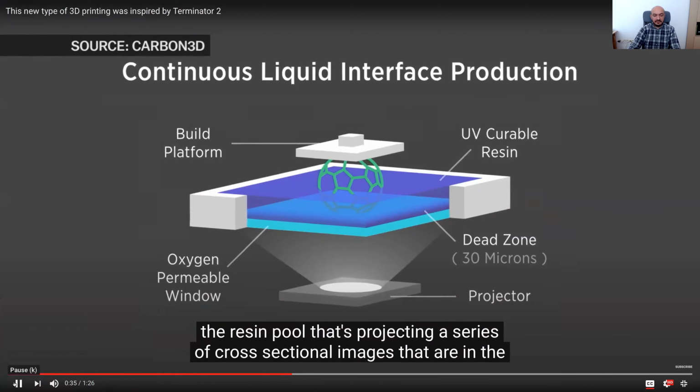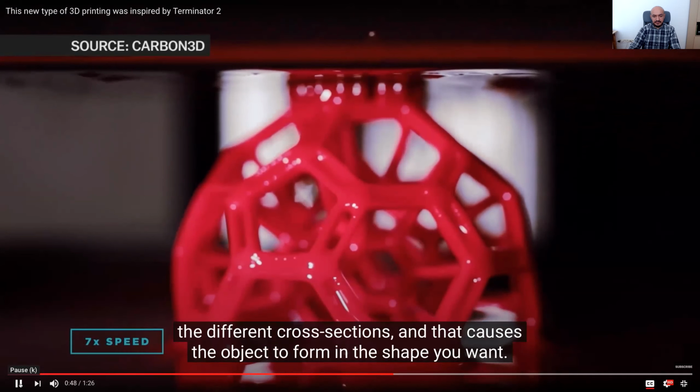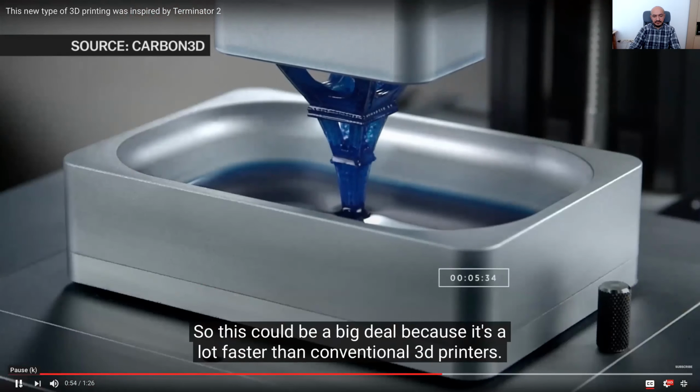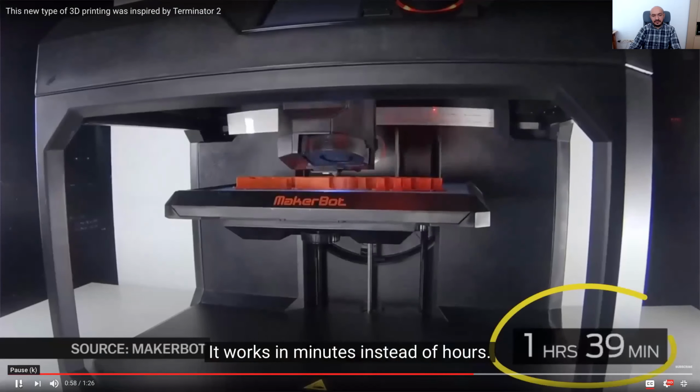Sectional images that are in the exact shape of the object you want to make. So as the platform slowly moves upwards, the projector moves through the different images, the different cross sections, and that causes the object to form in the shape you want. Wherever there's ultraviolet light hitting it, that's where the plastic solidifies. So this could be a big deal because it's a lot faster than conventional 3D printers. It works in minutes instead of hours.